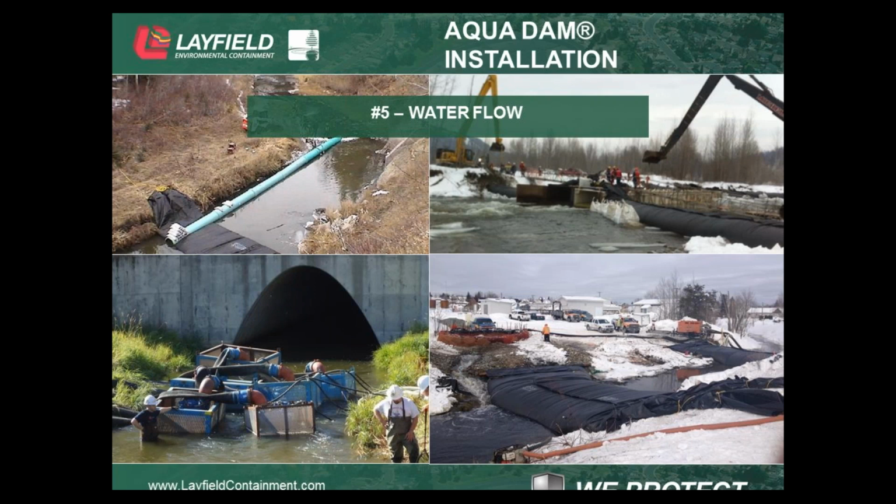The bottom right picture, we've got another pump diversion project. We're diverting water flow. We're putting it into a sedimentation basin to allow any silts or anything that are being pumped out of the creek to get dropped into the sedimentation basin. The water then flows from the sedimentation basin back into the stream, and they're isolating their work area. So that's what that picture is. It shows a sedimentation basin where they've got some hay bales, pumping water into it. It's filtering the water, and cleaner water meeting their suspended solids requirements is being passed below the downstream aqua dam and continuing on in the stream.